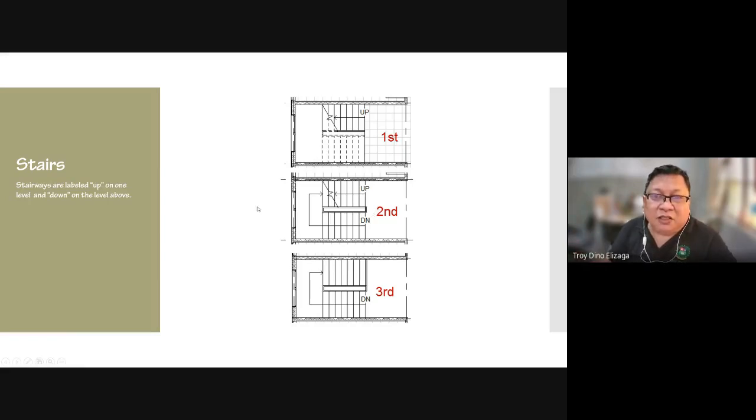In the second floor, one side goes up, the other side goes down. So you still cut it, but this time you draw the rest. Say going up is cut here, because you know it's 1.2 from the floor, you cut the whole house, and then going down you see everything. So you also have an arrow that says down. Okay. In one book they call this the Hong Kong style. I don't know, maybe this is used in Hong Kong, and the author is influenced by that, no?